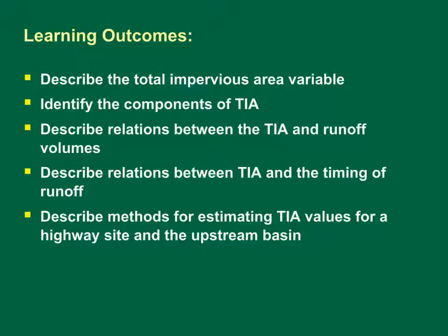The TIA primarily is comprised of roads, buildings, parking lots, driveways, and sidewalks. Regression equations relate the average, standard deviation, and skew of runoff coefficients to the total impervious area. These values are used to generate the population of runoff coefficients used by SELDM. The change in runoff coefficients with increasing imperviousness is small for low TIA values and increases as TIA gets large.